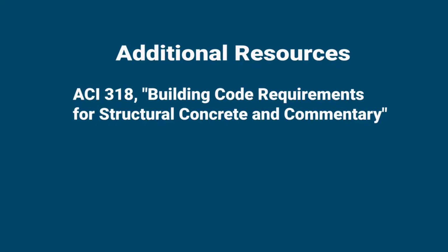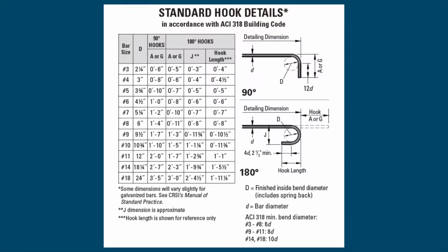If you don't have specific product or shop drawing guidance, concrete codes such as the ACI 318 or CRSI documents provide requirements regarding the allowable minimum curve internal diameter dimensions when bending bar or wire. It's important for employees to know the proper rebar bent diameter for each drawing. It's also important for employees to know how to adjust the machine to achieve that proper diameter.